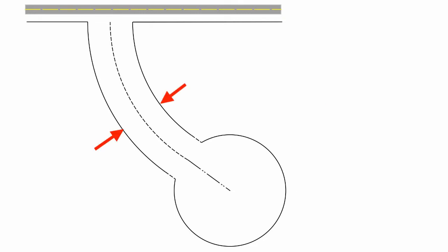The minimum width of the right-of-way is 50 feet in this town. The minimum length of a curve radius is 150 feet measured at the center of the road. The minimum radius for the outside edge of the right-of-way for a cul-de-sac turnaround is 60 feet. The minimum radius for a transition curve is 20 feet.